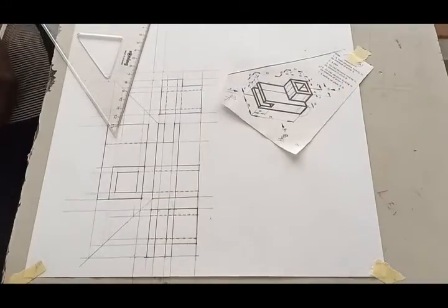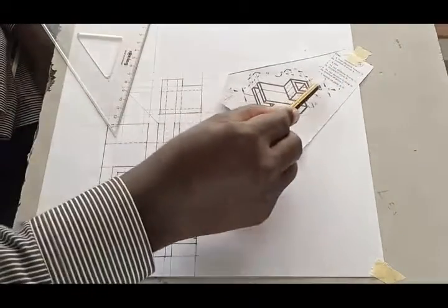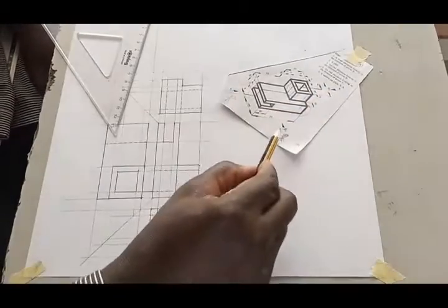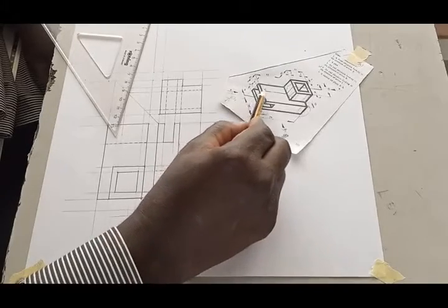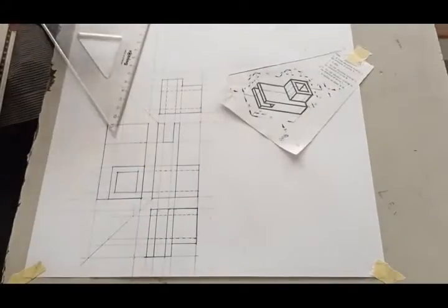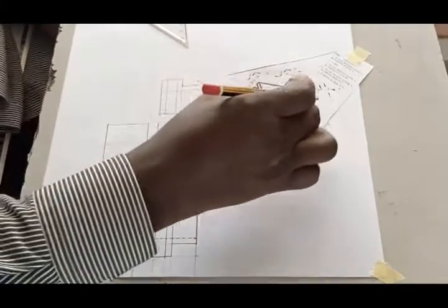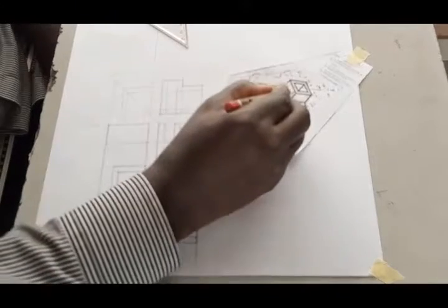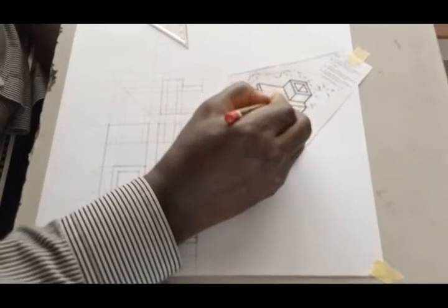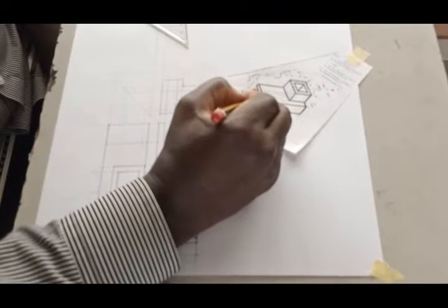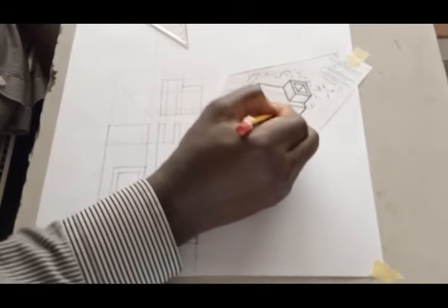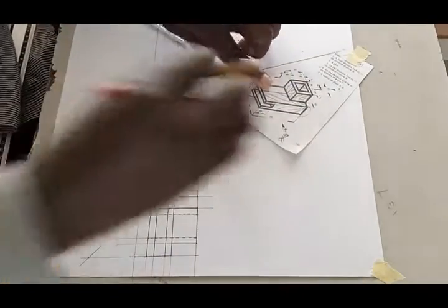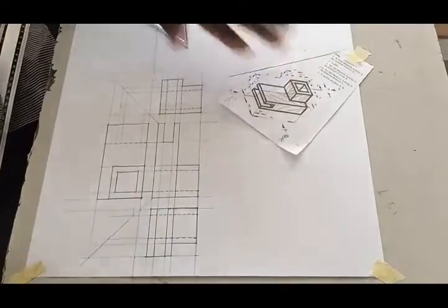Now finally, a section on plane XX. This is X. You can see X is facing the direction of arrow A, like this. It's going all the way through, cutting like this. Now what do you see? You are going to see exactly the same thing when you are viewing from arrow A, but we have assumed that this portion has been cut off. The whole of this portion has been cut off. So we are left with only this side. You assume that you have removed this side and you view the same thing.